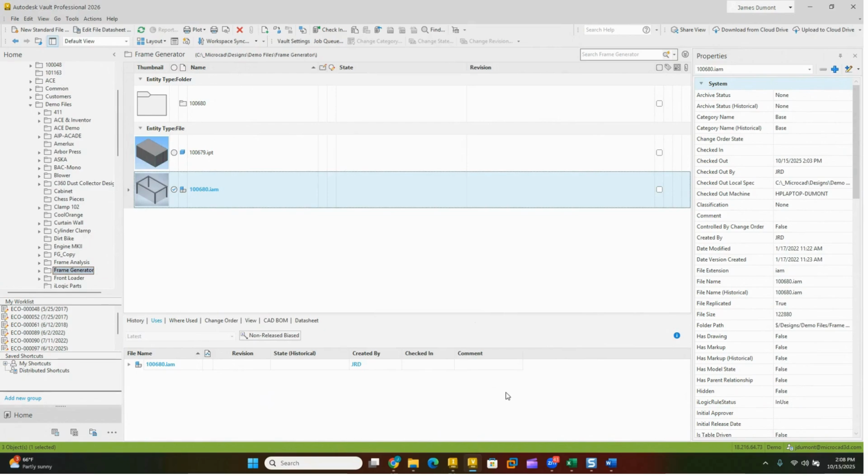And especially when you're using the design accelerator features, it's going back. If I open up Inventor and I open up an assembly, I get bolted connection 1. And again, the next one, bolted connection 2. Tomorrow I do the same thing, bolted connection 1. I try to check those in, it's a problem, they don't work. So you have to be conscious about renaming your files. But again, you can shut that switch off. You can work that way. It's just a recommendation to try to work with unique file names, just so that there's no chance of opening the wrong file.